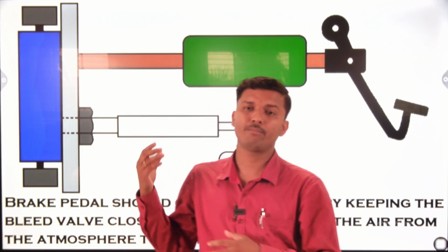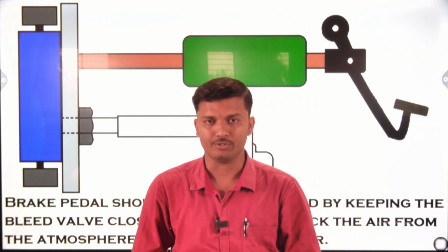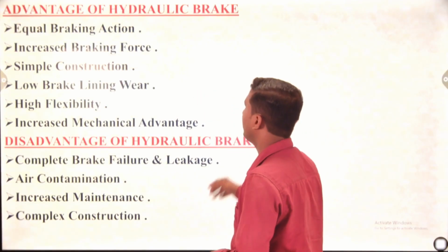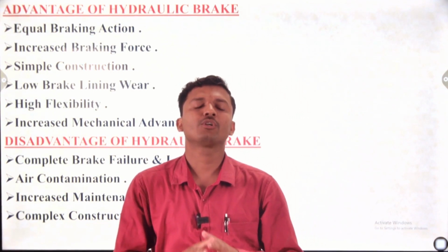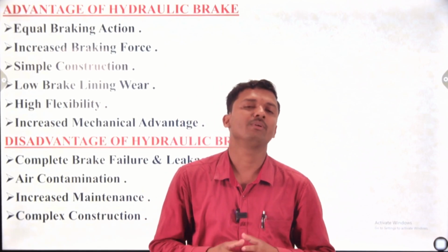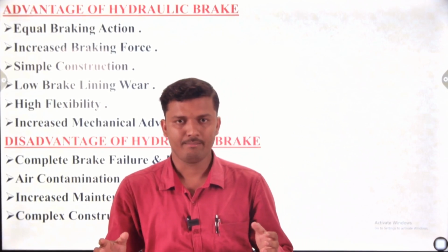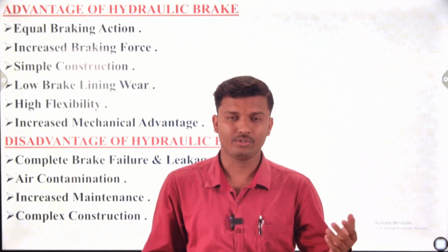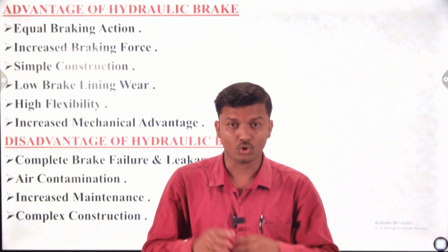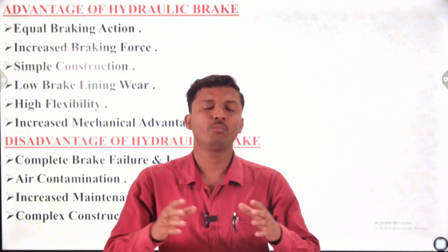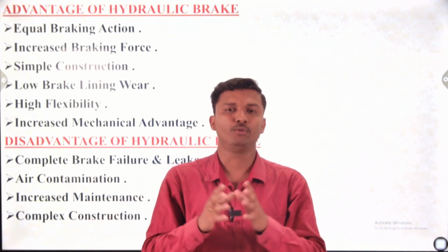Okay, this is all about the working principle of the hydraulic system. Next, we are going to discuss the advantages and disadvantages of the hydraulic system. The advantage of the hydraulic braking system is equal braking action. As per Pascal's law, which I already discussed, the forces are equal, so there is equal braking action in all the wheels, with the forces distributed in parallel.